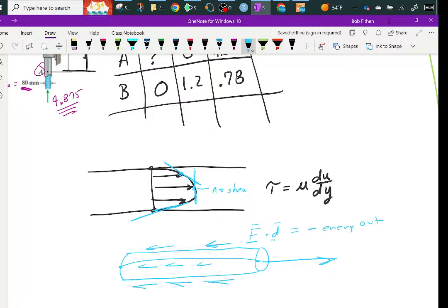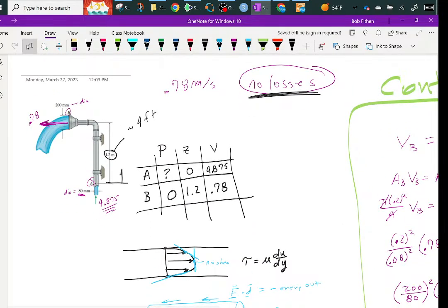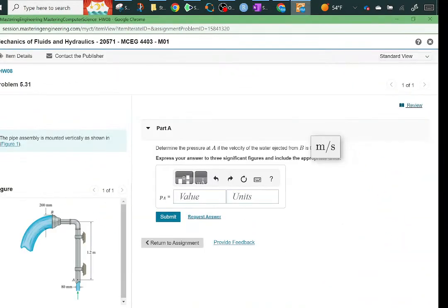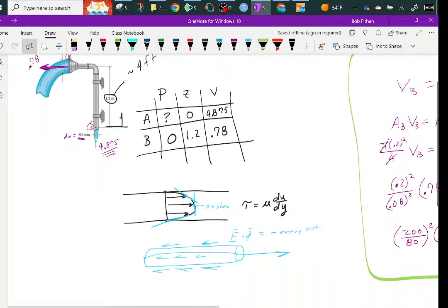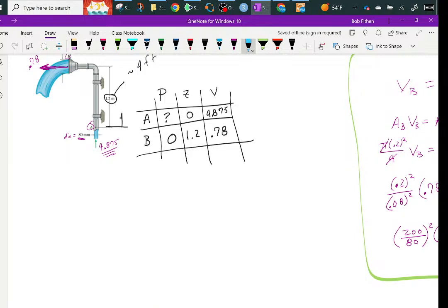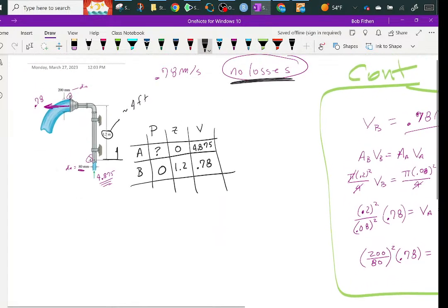So in fact, he should have addressed that. He should have just used the words that said, assume or envisage slow flow or no losses. That should have been a wording that got put in there. And that's actually pretty important. So the shear stress is what's going to cause this loss of energy through that pipe. I'm going to talk about that in a second after I get done how it's dealt with, but that's another chapter ahead of us. But there's no reason to not include that now.